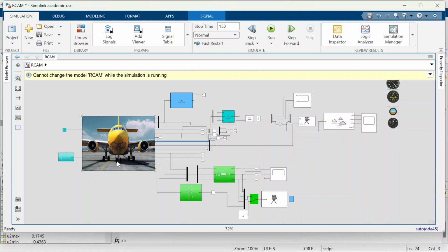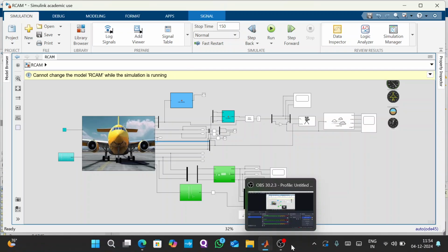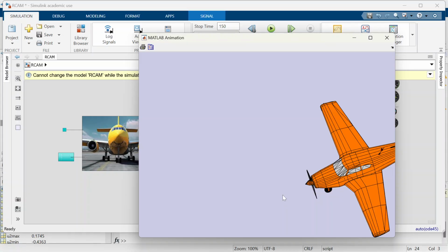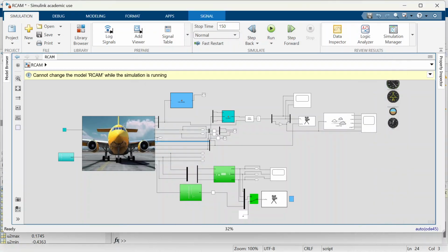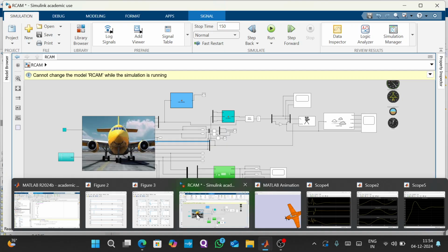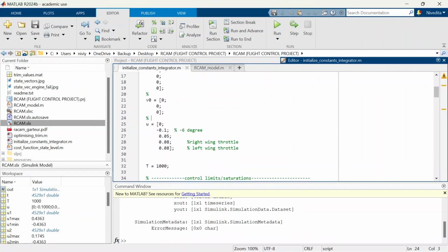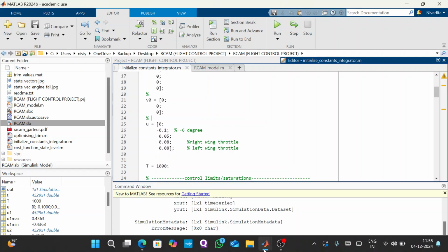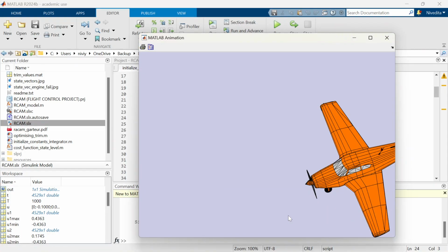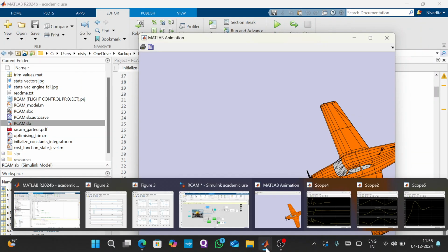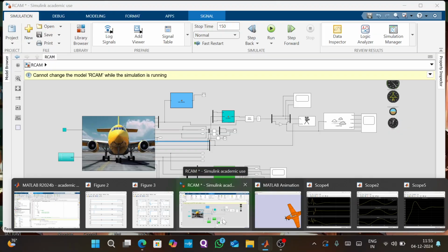And there is a limitation. The aircraft won't deflect above 25 degrees. So we can input the aileron, tail, rudder, and two throttles here. What we give as input here is not time varying. After we run, the aircraft will perform according to the same input. But when we want to change the pitch rate or the angle